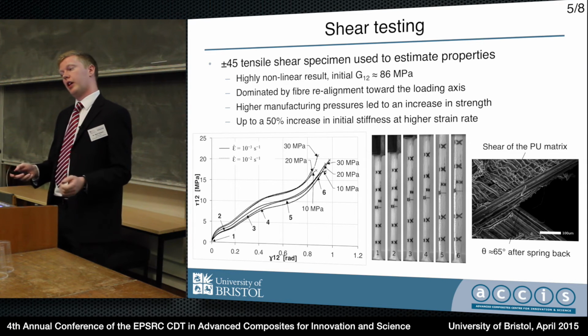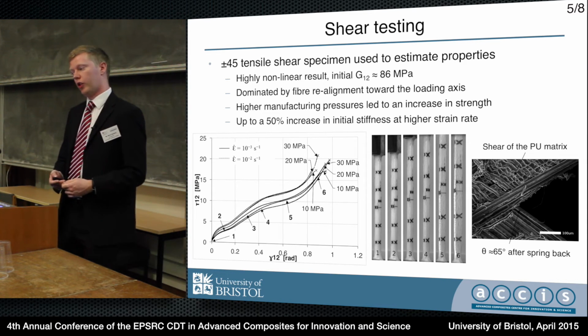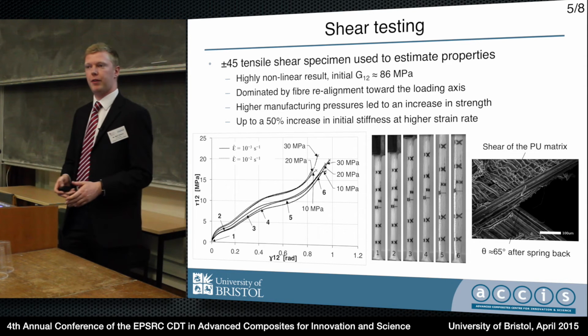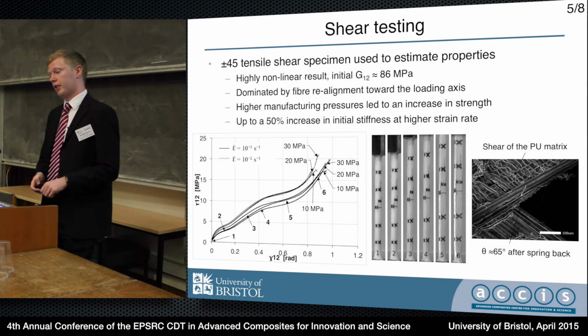I also did a quick investigation on the increasing strain rate, and I noticed about a 50% increase in stiffness due to an increase in strain rate.